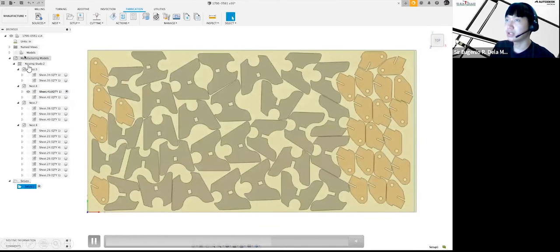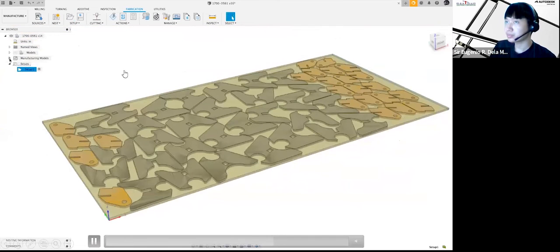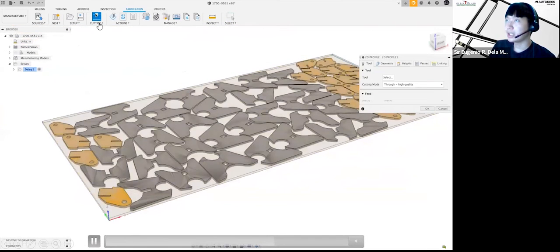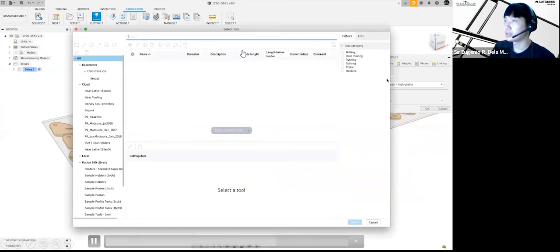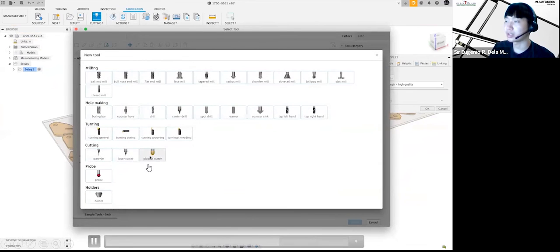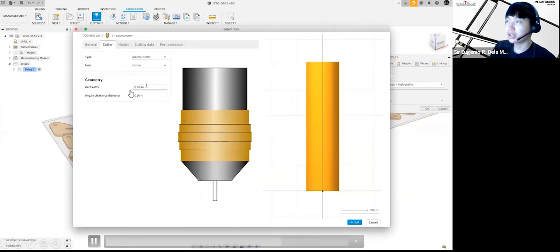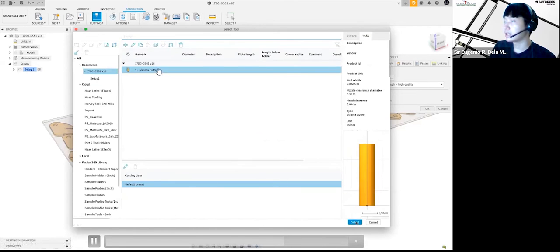Yan, so punta lang tayo siguro sa mas magandang view. Click natin, programming, yan, named view. Ayan, so makikita natin na we have here sa tab natin, no, we have here the cutting operation. Yan. So we can select tools that are supported, whether it is again water jet, laser, or plasma cutting. Yan, supported naman ng Fusion 360 kasi gagamit tayo ng plasma cutter, no. So let's say ang curve fit na gagamitin natin would be 0.0625. Ayan, then click accept.